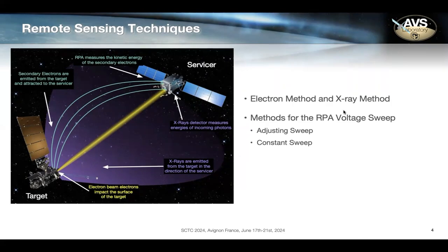The constant voltage sweep does not adjust the voltage step throughout the entire experiment. Rather, it is just held at whatever constant value we are measuring. So in the same scenario, for a voltage sweep between 0 and 1000 volts, the voltage step would just be set at 20 and the control would just run as is.